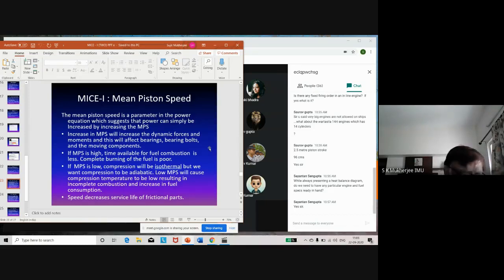Sometimes it doesn't burn, but you are told on board that you have to burn it. So designers have started making engines which can burn that poor quality oil which does not want to burn. They have given it very long strokes, and they have made arrangements to heat that oil almost to burning. Just before it starts carbonizing, it becomes like thin oil, and then it is injected.